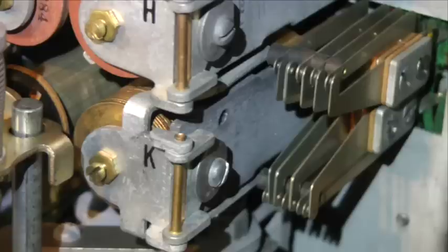It also puts direct ground on the called station sleeve lead, which maintains the operated condition of the cutoff relay in its line circuit until the call ends. In addition, this sleeve ground extends to all connector banks in the connector group, which makes the called station appear busy to any other connectors attempting to access it.